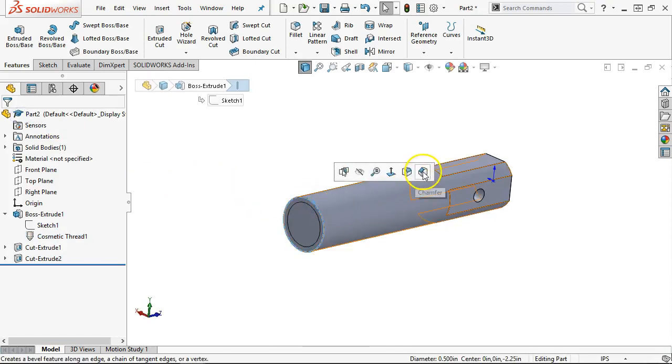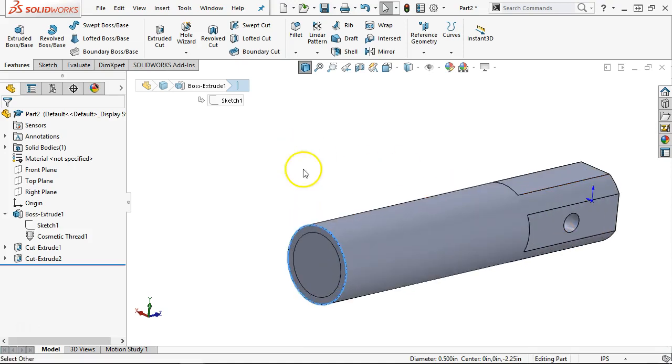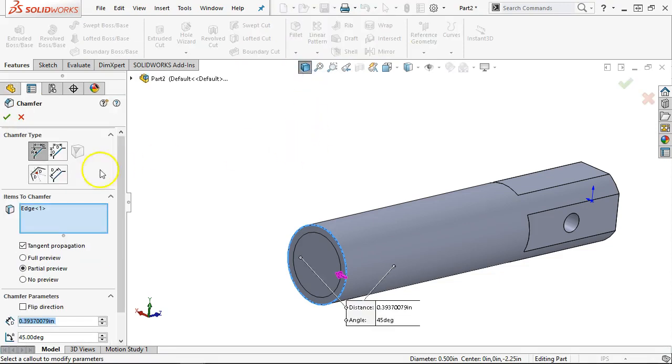Last is going to be the chamfer. And so we could have drawn, well, if we had made a revolve, we could have drawn the chamfer into the mix. But since we didn't, the last feature then under the features tab, we'll come about halfway over, find the fillet, chamfer is embedded under the fillet. Let's see, different styles of fillet, and I'm trying to think, 2018 also gives you the option, I'm not sure if it goes both ways, but to go from a fillet to a chamfer based on the same selection.